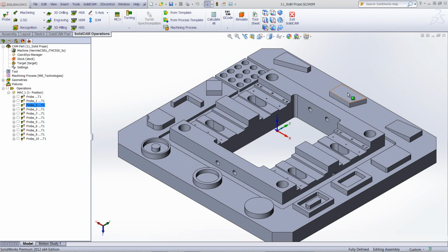I'm not going to measure every single aspect of this part; I'm just going to take a sample of certain areas. The reason is that the part was machined with a finish tool. The exact same tool did the finish on the entire part, so if I measure in specific areas, it'll give me a great indication of the entire part itself. Let me go now into my next operation.